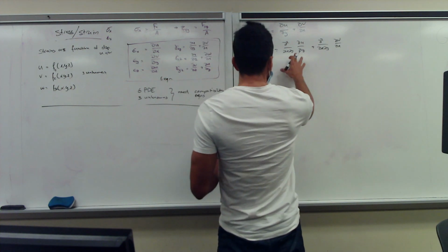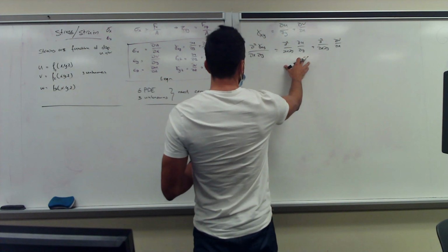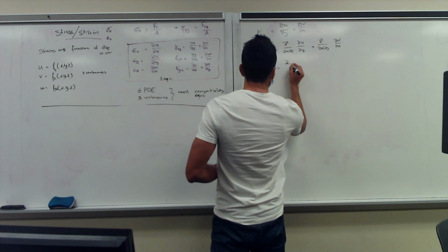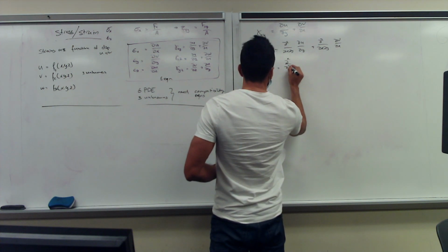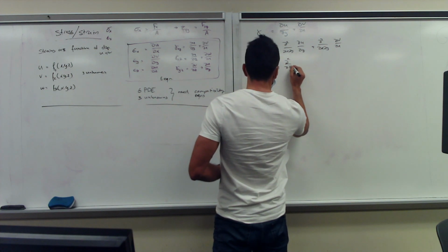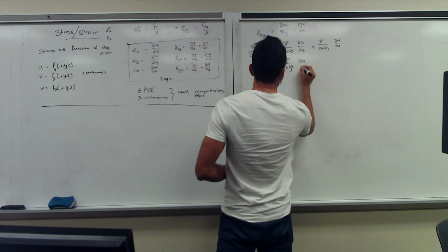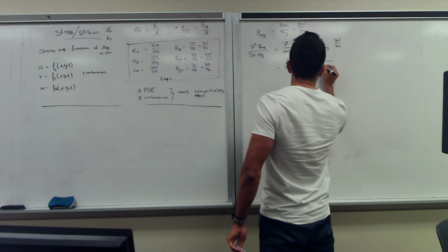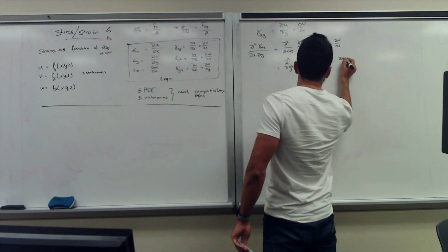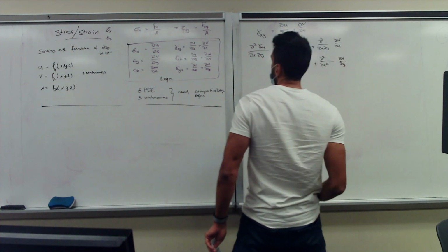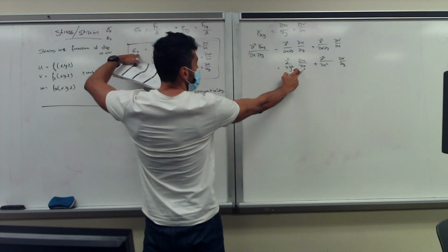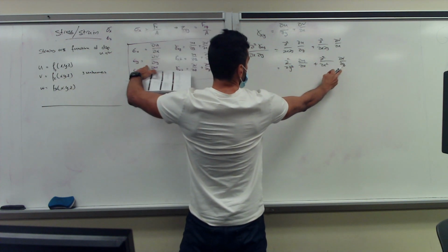We have two double dy's here, so we can take this and then use du/dx. So we get d²/dy² of du/dx plus d²/dx² of dv/dy. And from here, we know that this is nothing else than your direct strain in x, and this is your direct strain in y.